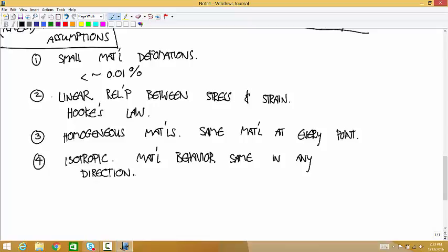So things like, well, wood, things with any kind of preferred grain direction, you have a stronger material with a bigger constant of proportionality in one direction than you do in another direction. The behavior is different depending on whether you're loading with the grain or against the grain. There's a lot of materials like that, but for the most part, engineering materials are not that way.